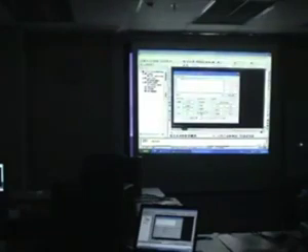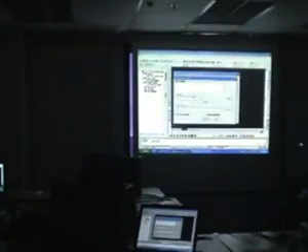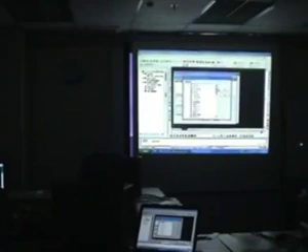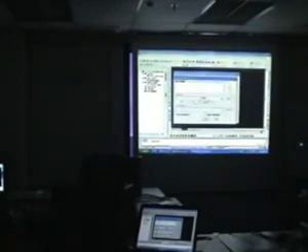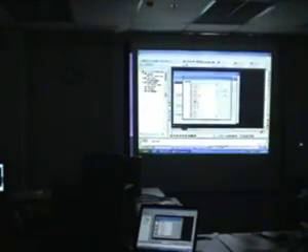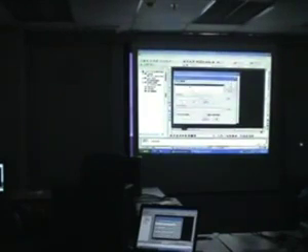I'm going to use report. I'm going to go to options. This is where we set our report template, meaning what's the first column, what's the second column, what's the third column. So I'm going to go to expression and extract x1. Add. So we've got our first column. Then I take the second one, that's y. So we've got x and y.